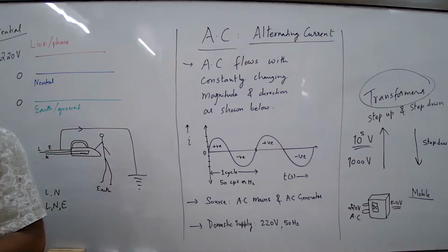From that, the wiring will be done in the entire building, then at house level. What is shown here is the house level wiring. This is the wiring in one room of your house. But before that, this is the connection till the energy meter. Every society has a meter room. These three things are till the meter. So what wire will come? You have an earthing wire, then the live wire, and the neutral wire. Let's start from here.